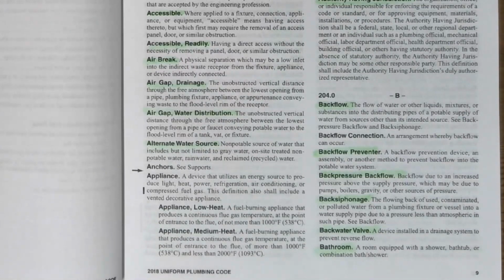So you've got this tub basin filled with paint water, and your hose is sitting in there because you have it connected to your faucet, and yet you're still running the water. All of a sudden, the pressure drops down to nothing, and the water is being drained out. Well, since there's no air break, which is the separation between your drinking water and a contaminated source, it's essentially going to siphon out that sink basin, creating contaminated water, and it's going to go all the way back to the city main and contaminate the city main.